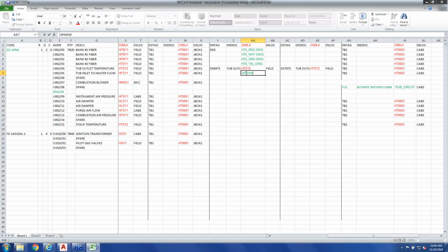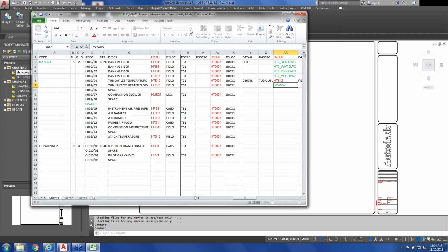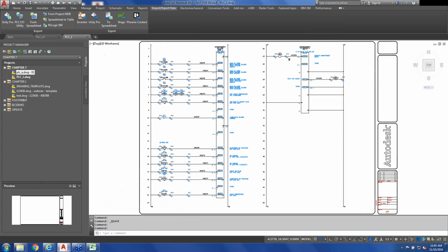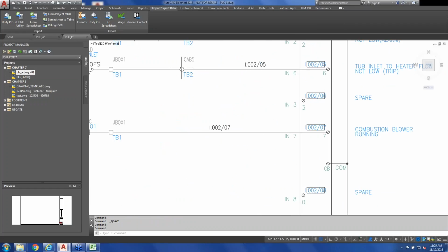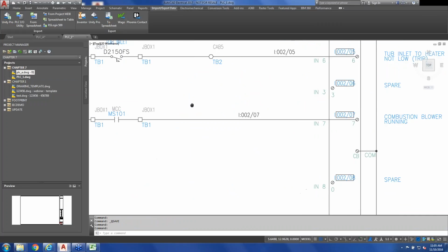Following that, you'll have a series of W's and X's that tell AutoCAD Electrical how to trim or keep the wires there. So what this is showing here is that within my ladder, where that wire is going to be drawn, as an inline device here, it's going to be drawn between these two locations. And what it's going to do is it'll draw a wire in here, and the W's and X's will trim or keep the wires.